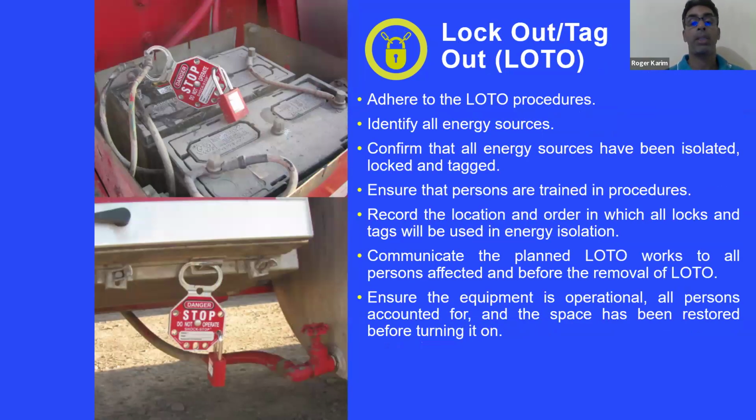Lockout tagout, especially for energized or pressurized pieces of equipment and pipelines: confirm that the controls are locked out and tagged out, and the system is de-energized or depressurized, as the case might be. Lockout tagout normally works in conjunction with your work permit system. Oftentimes, depending on the type of work, if it's a piece of equipment, you use lockout tagout in addition to your permit. So a condition of the permit will be to ensure that your lockout tagout is put in place.